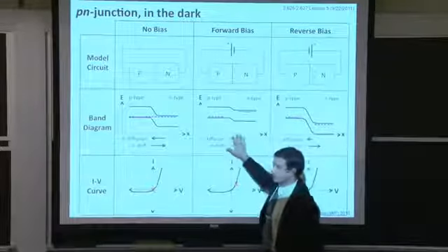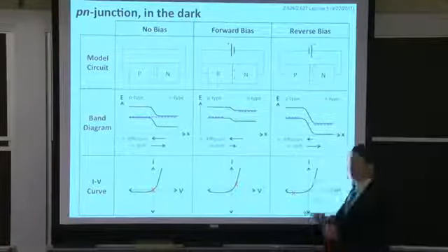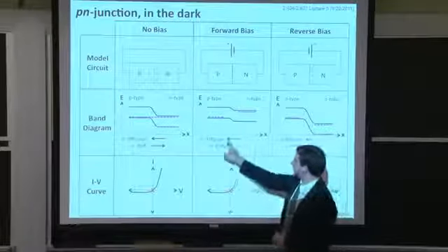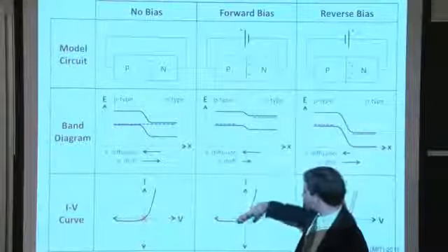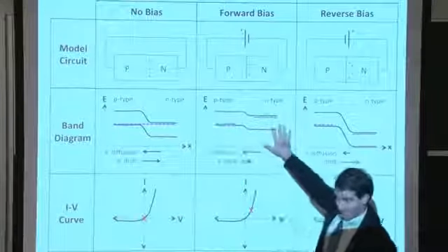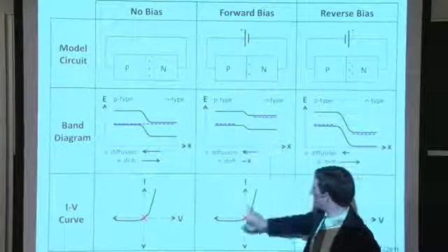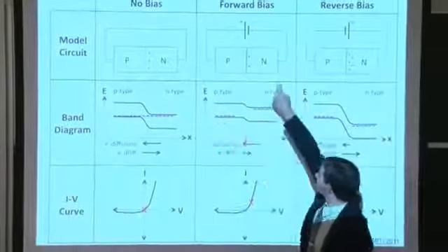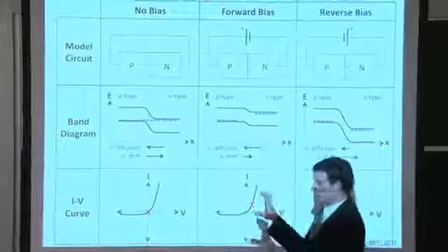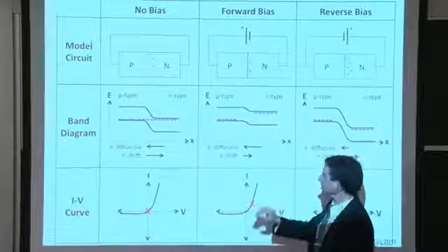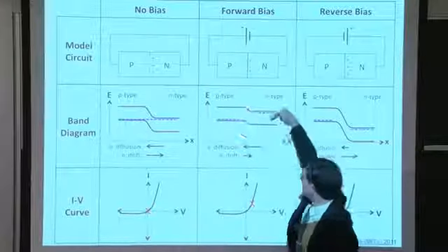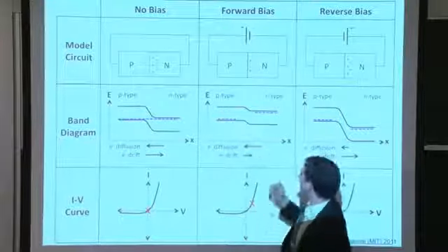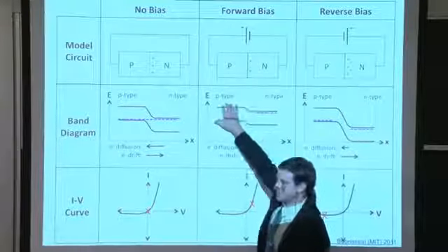And that's why we have this diffusion current dominating in the dark. So we have current flowing from right to left. In the illuminated case, we'll have all of our carriers traveling from left to right. And in the dark, this is the only case in which we have carriers traveling from right to left. And it's happening because we're using that battery in the dark to change the chemical potential on either side, which in effect reduces this barrier height and allows carriers to diffuse from the n-type and the p-type. So you can think about it as forcing carriers up the junction, right?